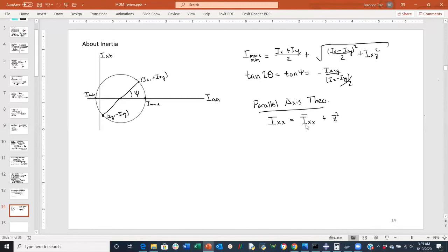By the way, this is bar, as in if you take something that has this sort of cross section, you split it into 2 parts, 1 and 2 here, you are going to look at, in the x direction, where's the centroid of shape 1 and shape 2 here, and obviously you sum the inertias in the x about the x-axis for all the different sections you split your cross section into.